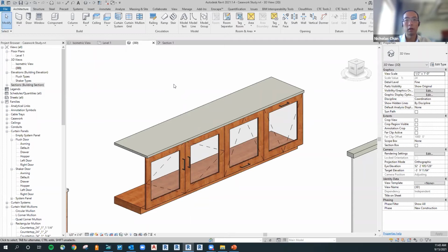The fact that it is a curtain wall might allow us to help filter some stuff out, because we don't typically use curtain walls in our other doors and windows. In our offices, we use doors and windows, and the only instance of curtain walls is really this use here. That is a great question. You're right, if you want to be a purist, it's not a category of casework. It is a wall. But to overcome it, a workaround would be to just use filters. Create a wall filter for casework and filter it out of schedules or views, however you want to use that filter.